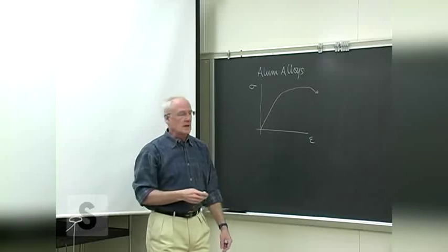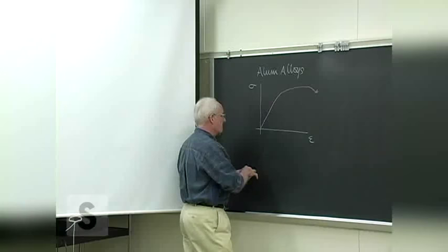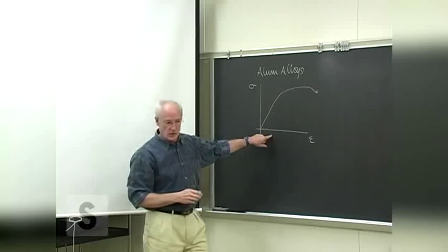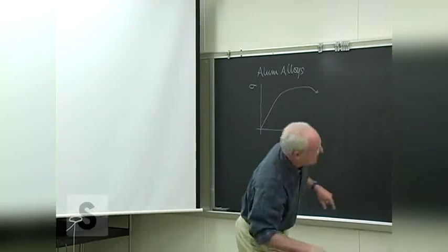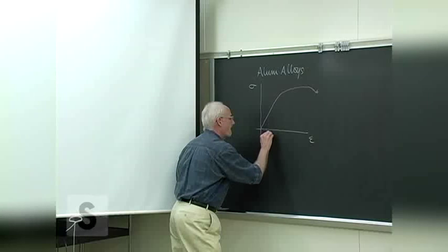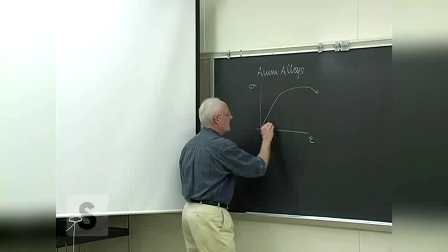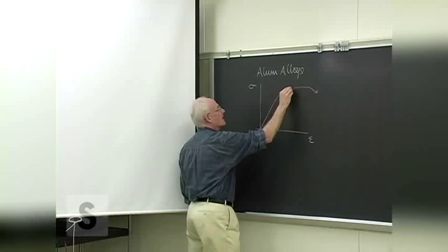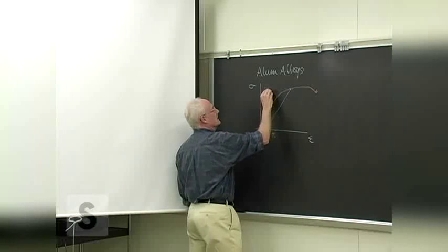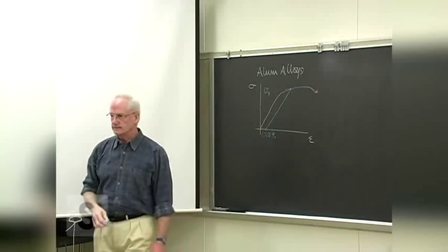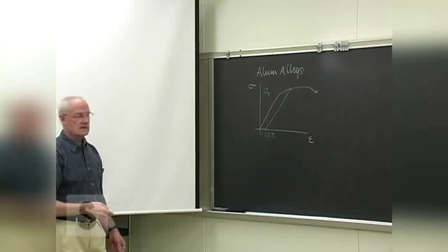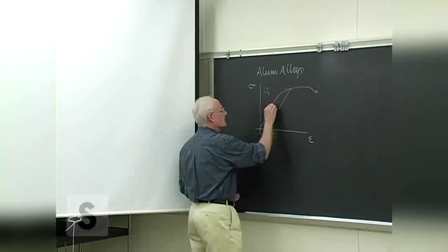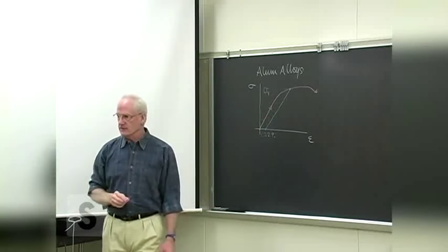So one thing that's commonly done is a particular strain is arbitrarily chosen, something like, make sure to get the number right, 0.2%. And then parallel to the curve up from that, they can pick that off, and that's often given as the yield stress. One thing that's interesting about these type of curves, and partly why that is chosen, is that the test generally goes up the curve.